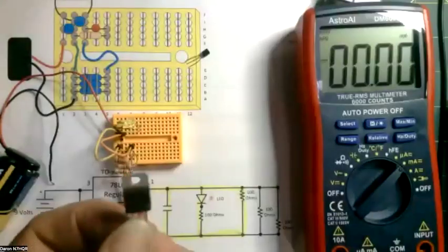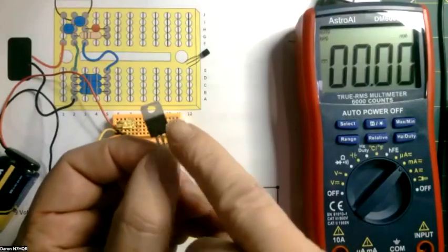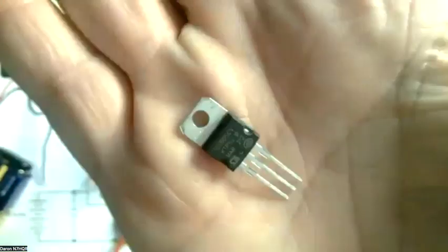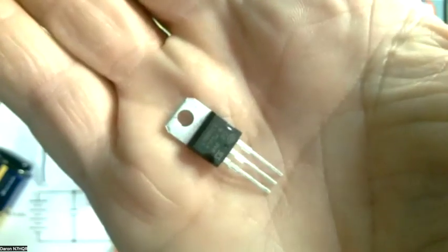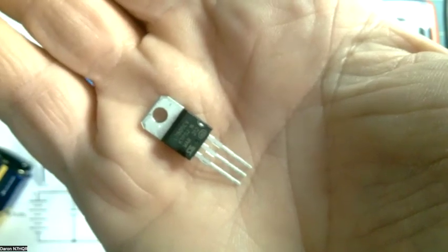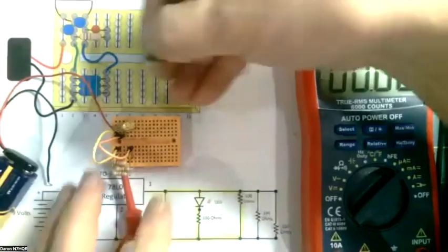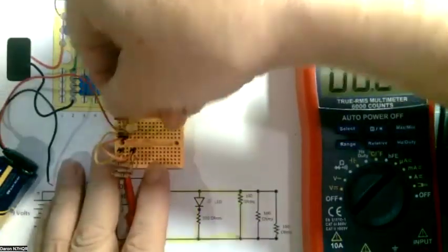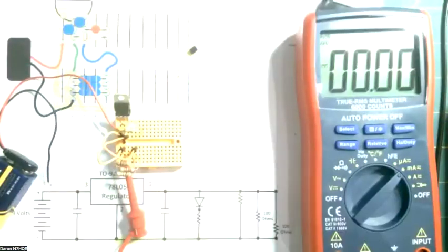And in this one, the pinout is different. So you want the writing on it. Maybe you can see that. I don't know. Hang on, let me get it up here. Oh, there you go. So there's writing on it. You want that to face towards you, or up, as we put it in that circuit. So we're going to drop that in the same spot that the other one was, but the writing is going to face up towards us. Yours went in fairly easily. I had a hard time getting mine in.